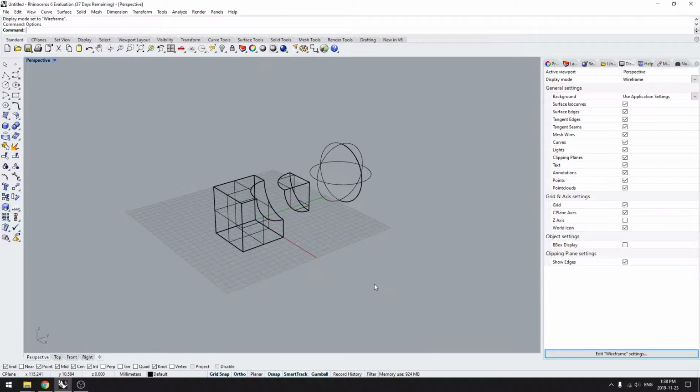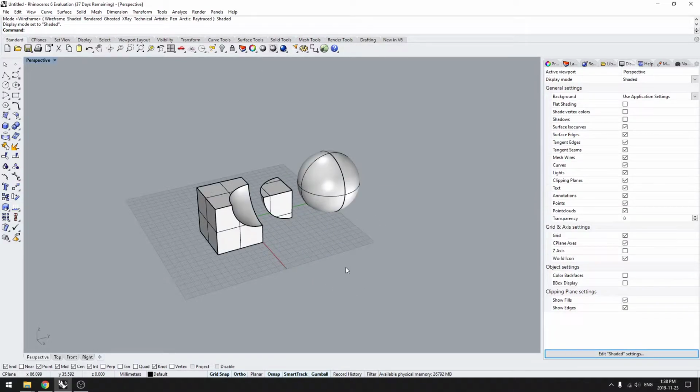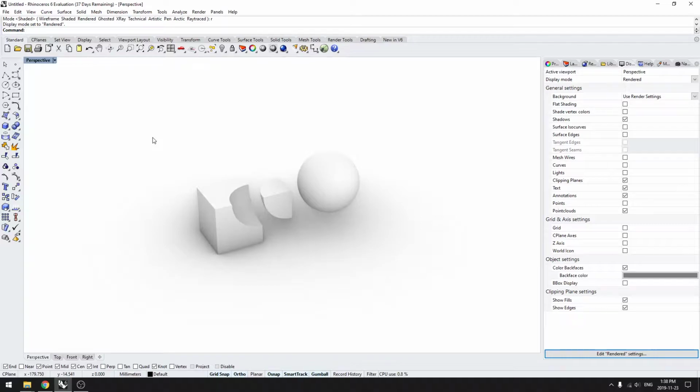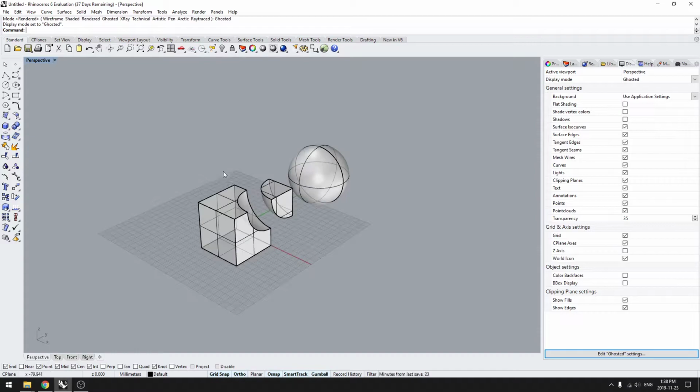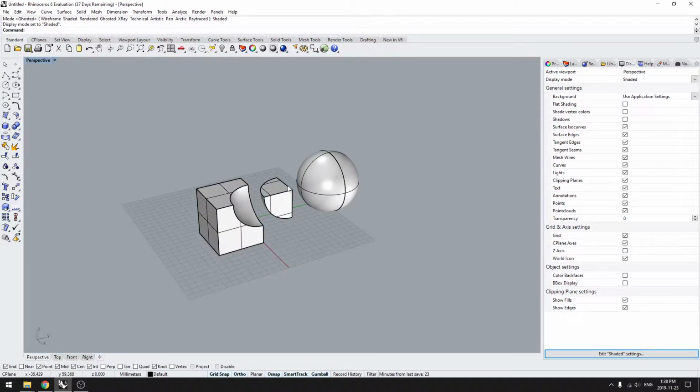And how that looks if you were to do it normally is you have to type set display mode, and then you have to choose the display mode. So over here, you type M, and then you choose a mode, right? And so maybe I want to go to render, I type R. So instead of going through that whole lengthy process, you can just go F1, F2, F3, or F4, right? And that makes things really easy. And you can do this for any type of commands too. So it's super useful and speeds up a lot of the usual commands that you guys use together.